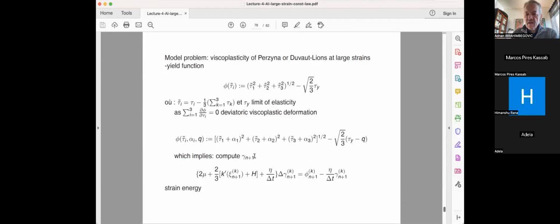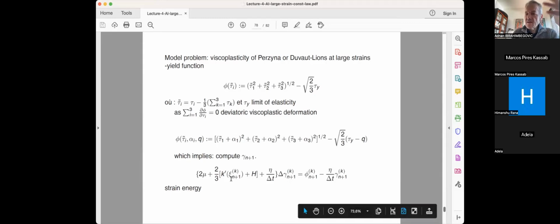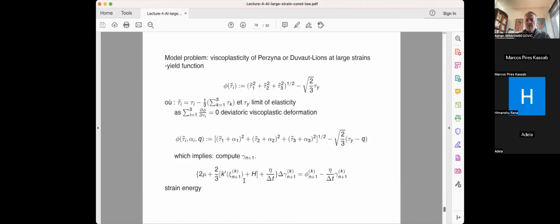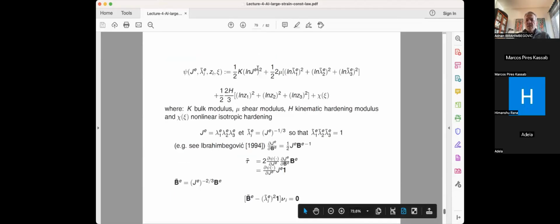And if I take into account, let's say, the contribution of viscoplasticity, it will affect the computation of my plastic multiplier. It could be as nonlinear as you want. You will have the tangent changing for every iteration. Then eventually I can get the final values and update them to the physical coordinates.